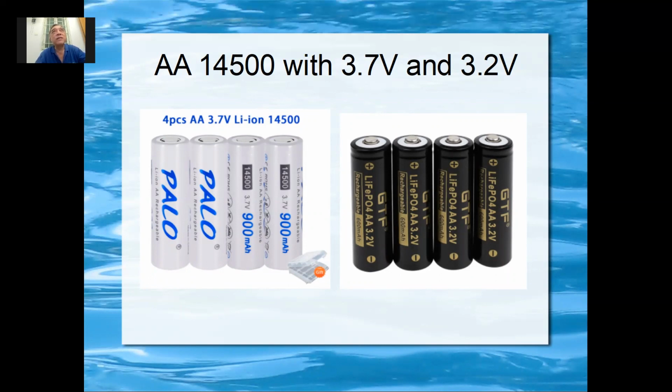So, but why are these batteries still around? Okay, these are created but without electronic circuit to step down the 3.7 volt to 1.5 volt. So it is intended for you to use one battery instead of two. Then the second one that you want to plug in is just a dummy, it's a short circuit. So you get very good power, and for the price of one. See, one of these is like $5. It's slightly cheaper than the one with electronics.